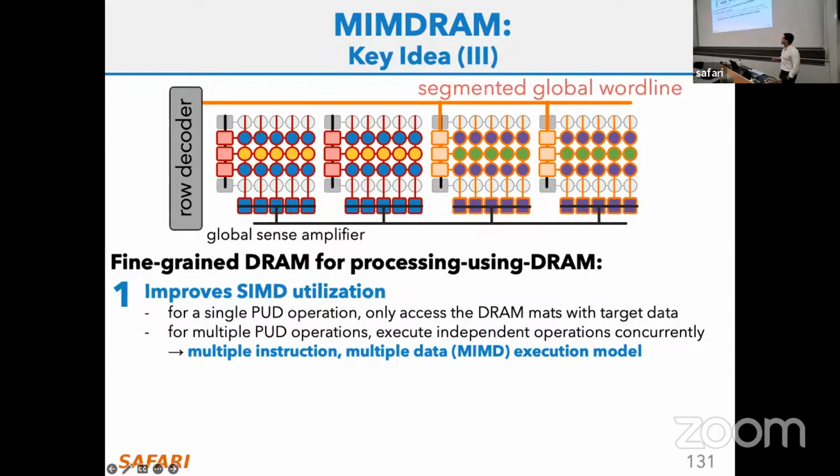So now, instead of looking at this substrate only as a single instruction multiple data engine, I can look at it as a multiple instruction, multiple data engine, because I have multiple instructions operating across different DRAM mats, and at the same time operating over multiple data stored across the different DRAM columns.